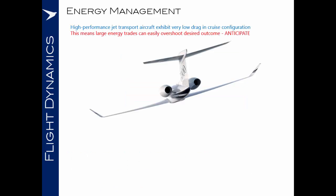In modern high-performance jet transport aeroplanes, great pains have been taken by the designers to minimize the drag in the cruise configuration. And therefore, large energy trades, trading that speed for height or height for speed, can easily overshoot the desired outcome. And as aeroplanes are heavier, there is a certain amount of anticipation which is required due to the inertia of the aeroplane, the tendency for it to continue in its existing condition.